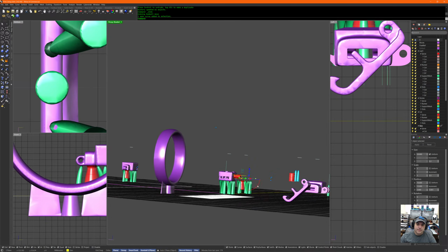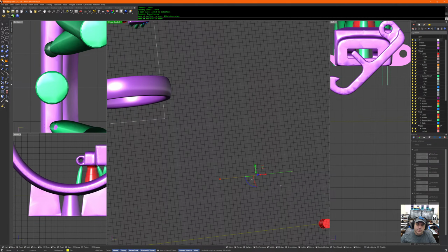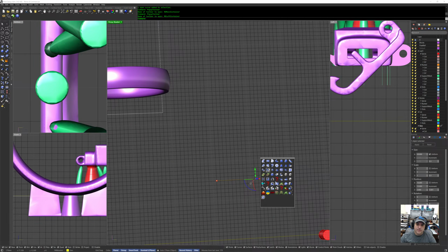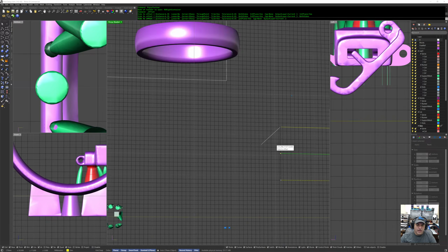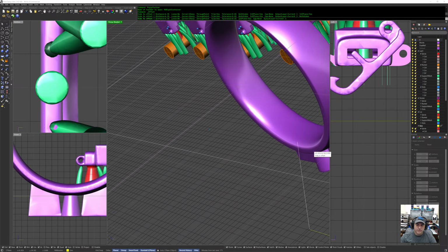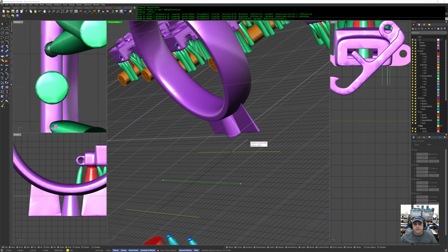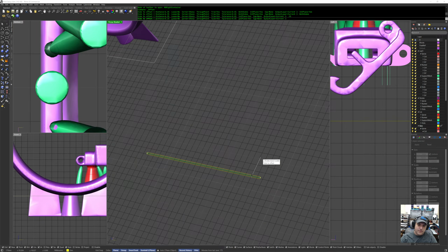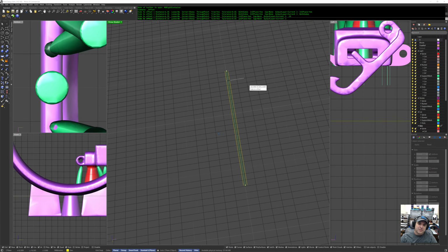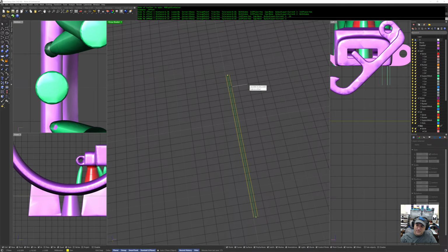And now I can build this, because what I need is to do an offset on each side, 2 of them. Offset curve both sides. And the top is how wide I want the top of this wedge to be. So normally that's like 0.1. But the wax needs a little more support. So let's say 0.15. That seems like too much. Let's say 0.1.